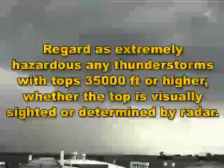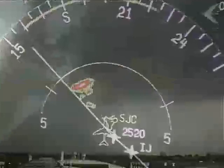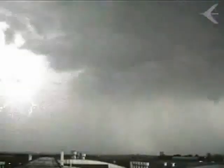Regard as extremely hazardous any thunderstorms with tops 35,000 feet or higher, whether the top is visually sighted or determined by radar. Playing within these golden rules, we can get the best from this valuable tool, and it can help us avoid bad weather conditions and keep our flights safer and more comfortable.